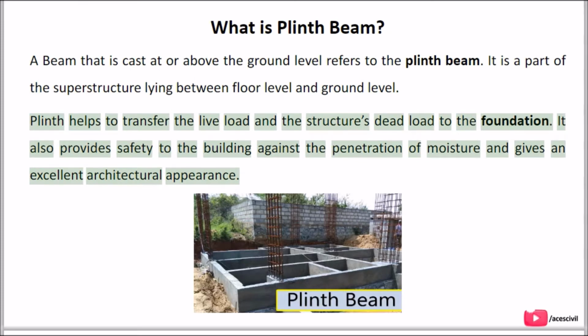Plinth helps to transfer the live load and the structure's dead load to the foundation. It also provides safety to the building against the penetration of moisture and gives an excellent architectural appearance.